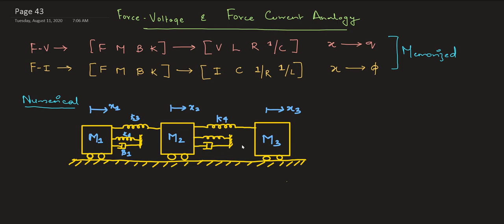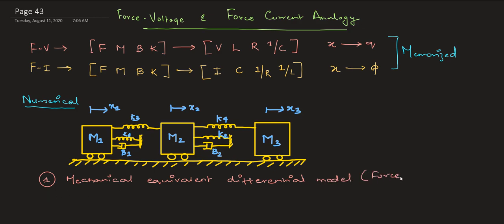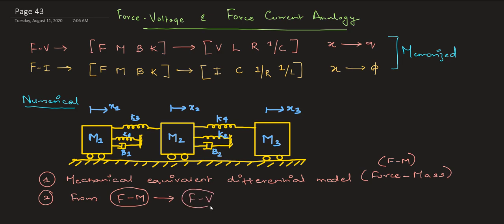So what were those rule sets? A quick recap. You have to isolate the masses separately. We have three masses M1, M2 and M3. After you isolate these masses, you need to look for the relative displacements, the displacements of the mechanical components between two masses. And finally, you need to write your force equation using all these things.